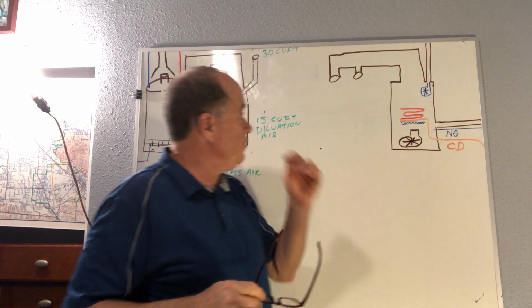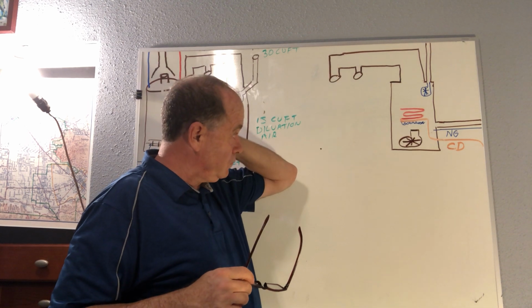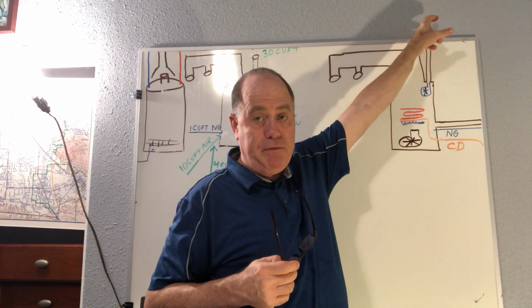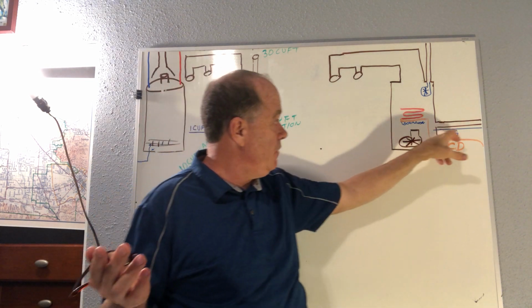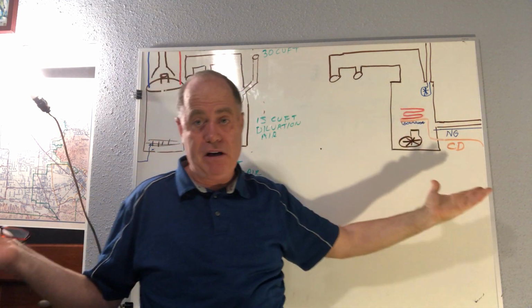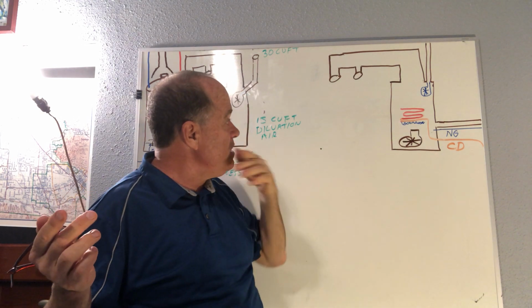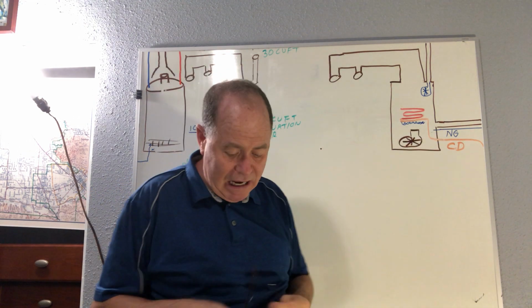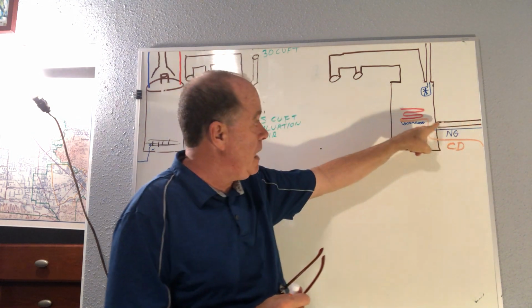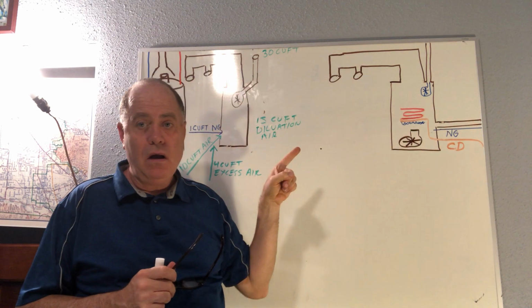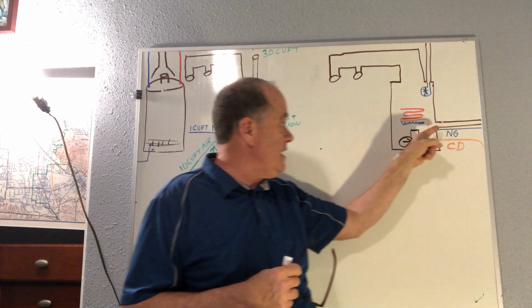And it's this: you've got, yes, a vent or chimney pipe that goes out the top to get rid of products of combustion. That hasn't changed. You have this blue natural gas pipe that's got to bring in natural gas to burn. But then you have another pipe, this intake pipe, that has to bring the air from the outside in.